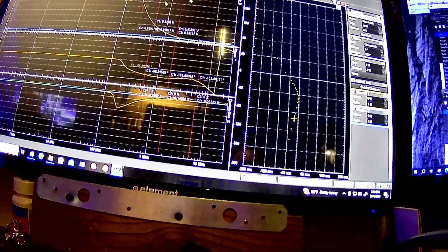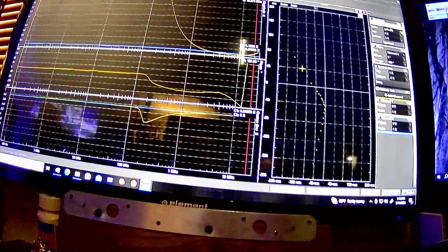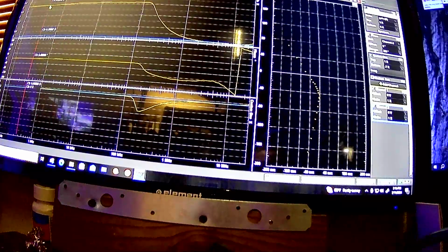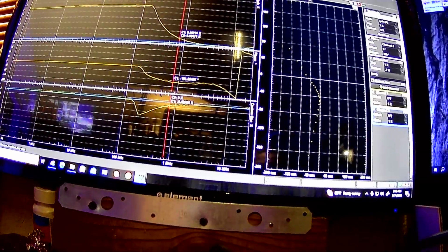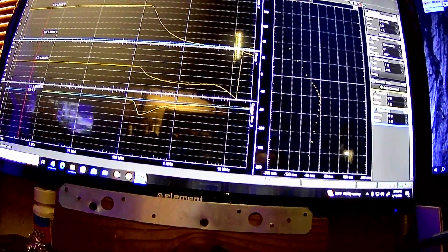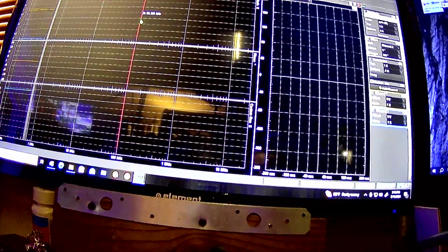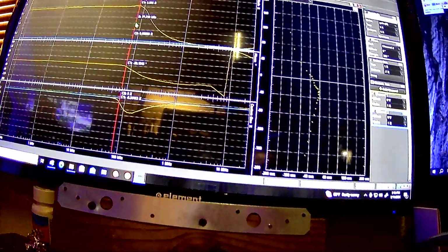So yeah, 130 kilohertz. But like I said, switching it back to gain, it's looking 3x across the board, no matter what voltage we set it at. You're looking for when that gain falls off. We can even try 5 volts, but it's probably not going to like that, because it's trying to put out 30 volts peak to peak, and it can't. The op amp can't do that.